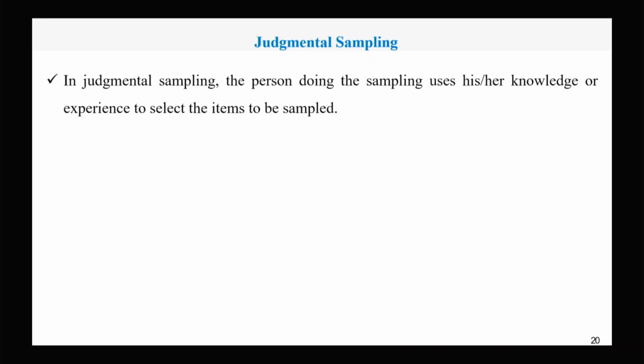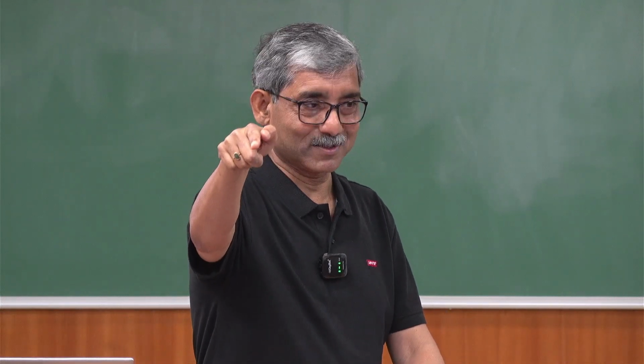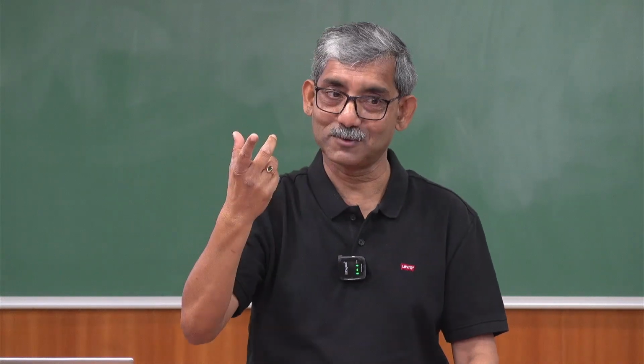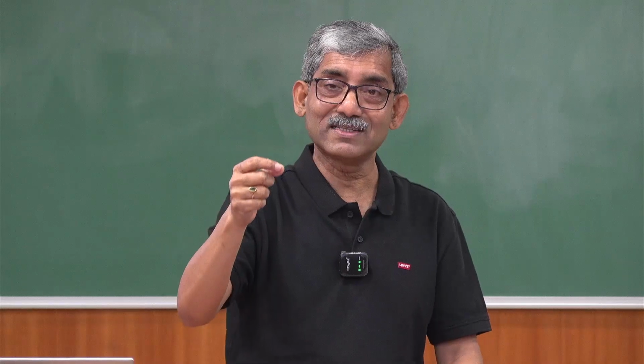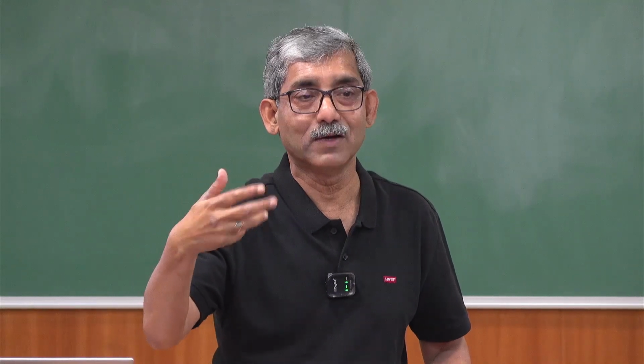And the last one is judgmental sampling. You use your own judgment. Like in a ring frame shed, one ring frame is creating vibration and giving poor results. You have checked the vibration level, or the maintenance people have set the machine correct. Now after that you want to test. So you go there, select that defective machine and take the sample using your judgment. What are you trying to do? I want to see whether it is giving better quality or not.